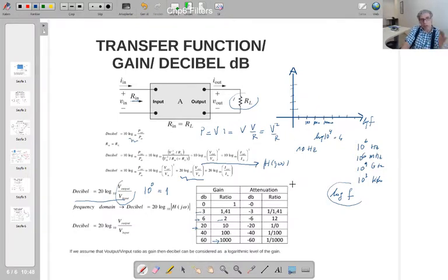So let's come to our filter characteristic case. This axis is going to be the modulus of H(j omega). Now we are saying, in order to show these high values on this axis, we are going to write here decibel, and this is going to be 20 times log 10. This is it. So that is what decibel is all about. In here, the ratio is positive, in here it is negative. Why is that?